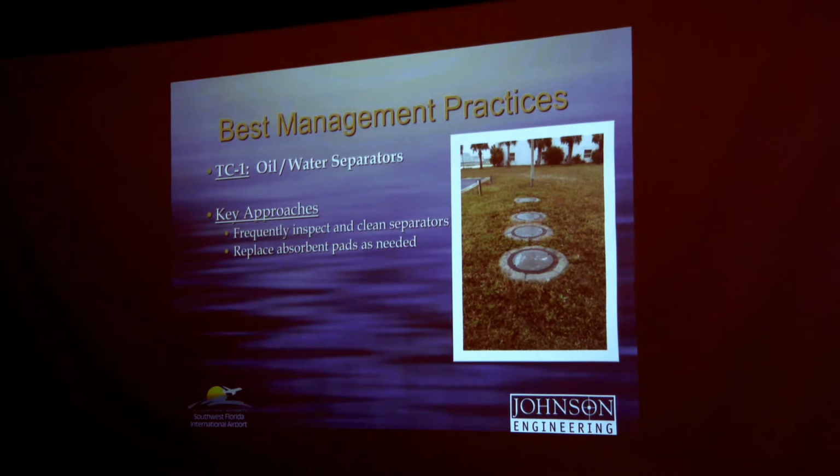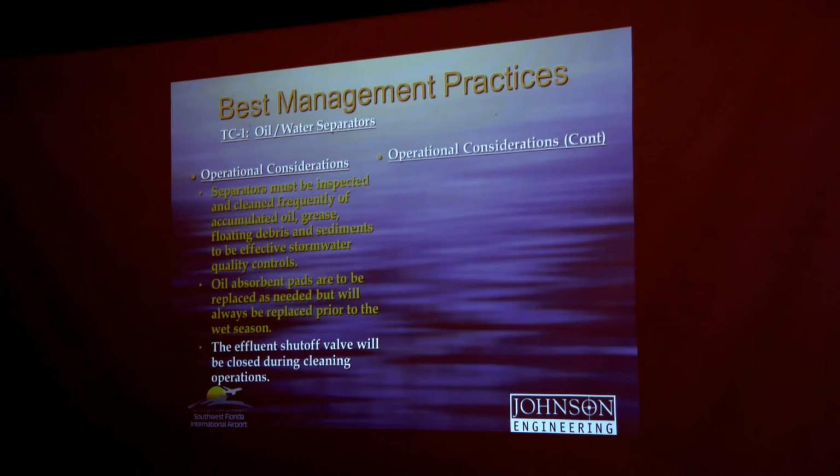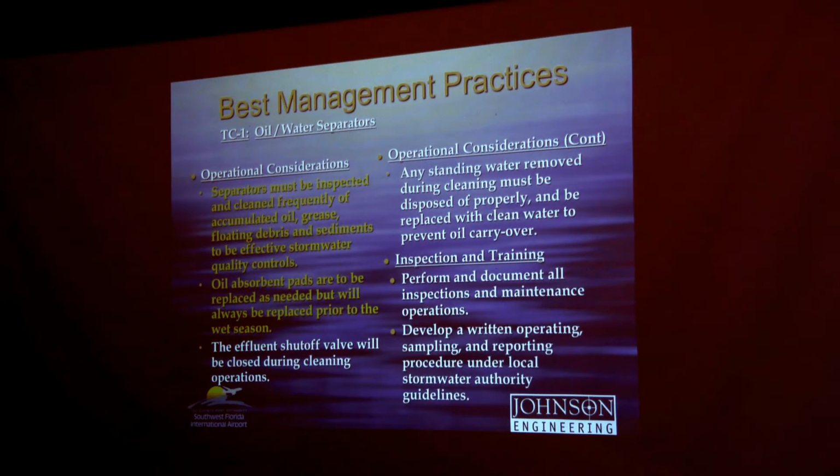The last BMP, TC1, is oil water separators. Key approaches include frequently inspecting and cleaning the separators and replacing absorbent pads as needed. Additional operational considerations include shutting the effluent shutoff valve during any cleaning operations. Any standing water that is removed during the cleaning must be disposed of properly and be replaced with clean water to prevent oil carryover. Performing and documenting all of your regular inspections and maintenance operations, and developing a written operating, sampling, and reporting procedure under local stormwater authority guidelines.